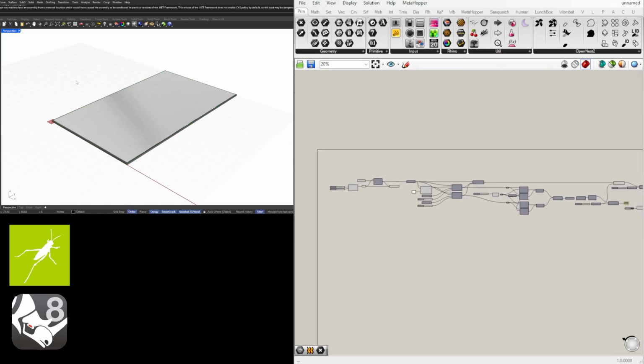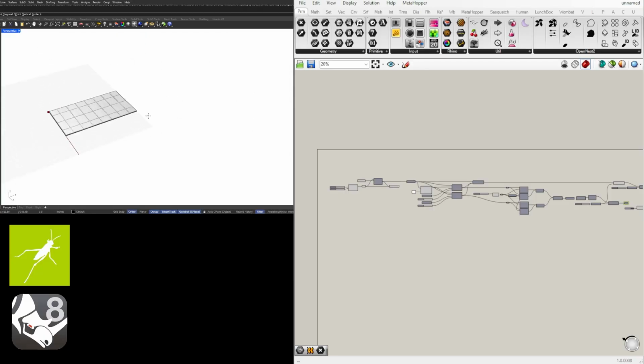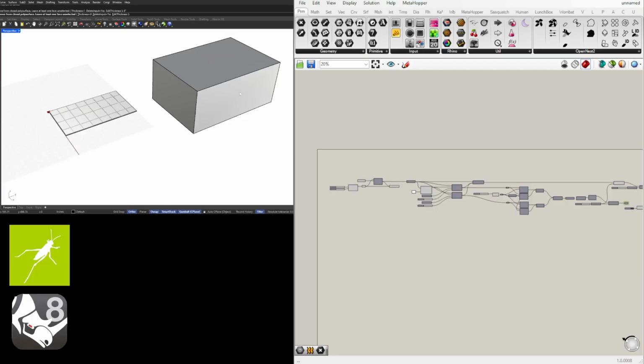And so let's apply this to something. So I'll go here to a box. I'll create a box all the way out here like this, make it 15 feet tall. Well, maybe 10 feet tall. I'll type in shell. What shell does is it creates a shell from a solid. So on this one, we'll make an 8-inch shell and remove this side and the top.